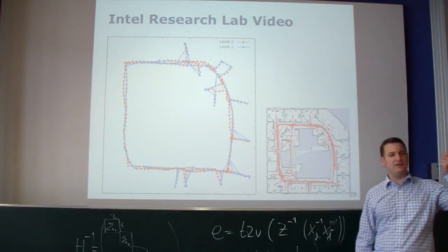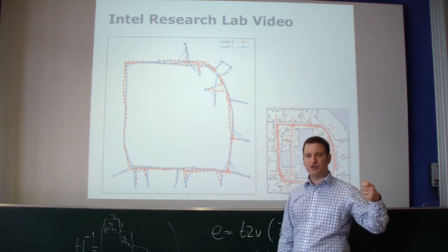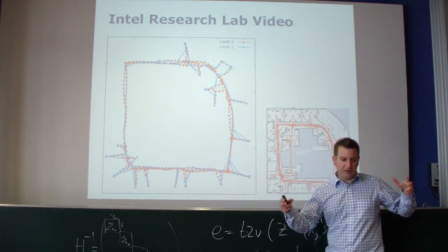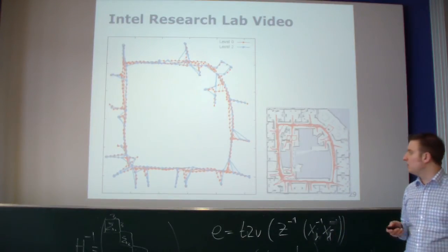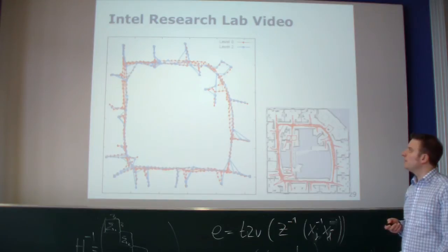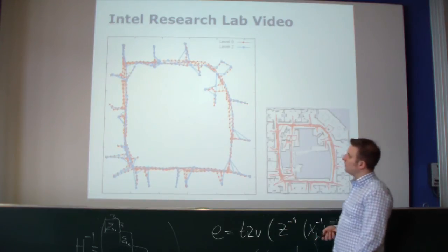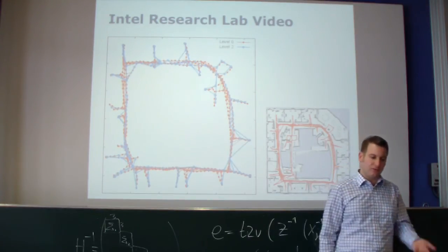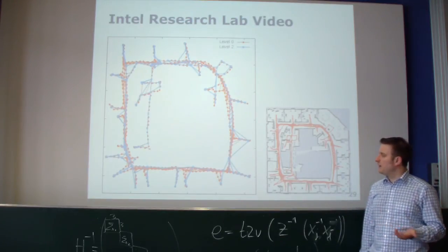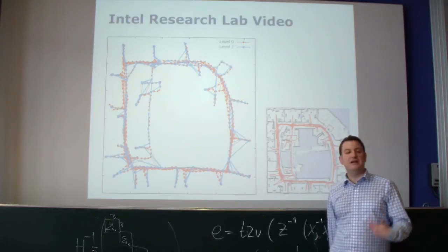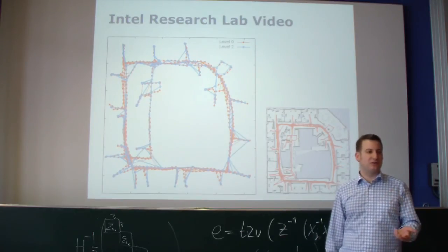It's just the case that we may update the edge information because they still belong to this local group, so you can assign this node again as belonging to this one local group. And then if you optimize only the blue graph, you involve much fewer nodes, much fewer constraints. Therefore, the optimization is substantially faster and is completely sufficient to estimate the rough structure of the environment.